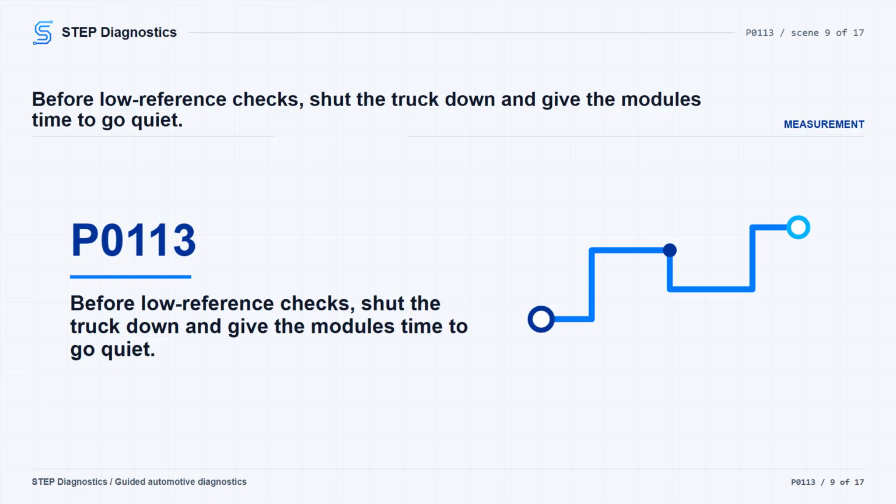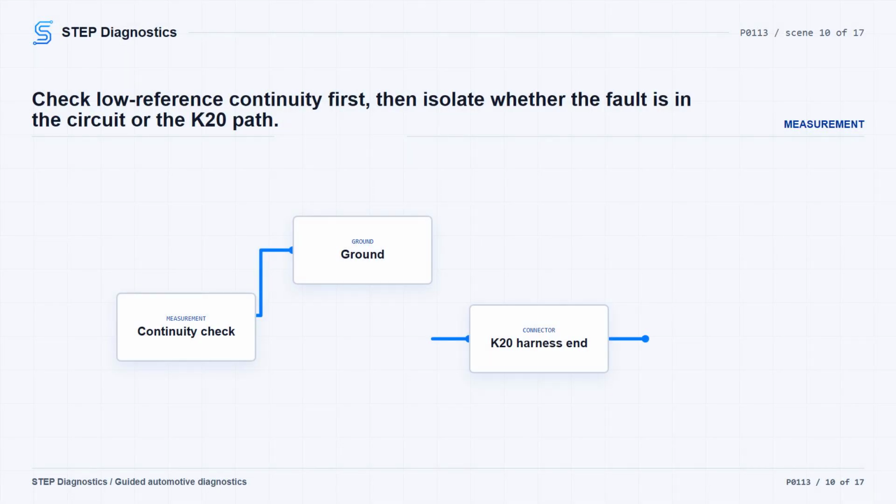If it is 5 ohms or greater, disconnect the proper connector at the K20 engine control module and test end-to-end on that same low reference circuit. You want less than 2 ohms between low reference circuit terminal 3 at the component harness and the other end of the circuit at the control module harness.